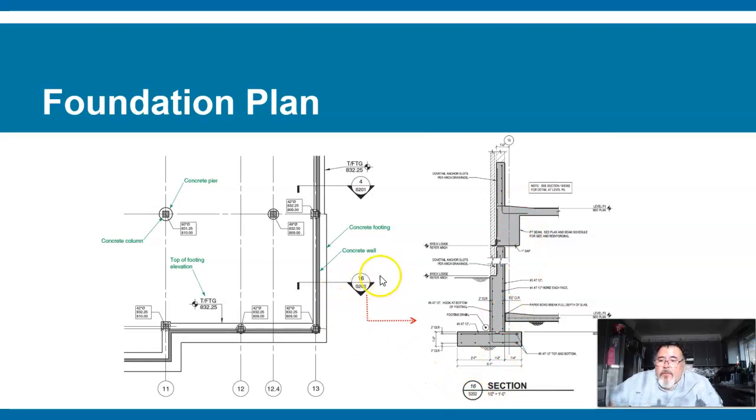Section 16 is showing you that the wall changes in height, the floor changes in height. You've got a level line and a level line for two different floors. You've got this footing and this wall that extends all the way up to another level of a footing at another level. So this one's detail 4 and this one's detail 16.